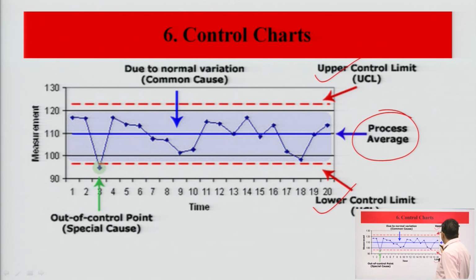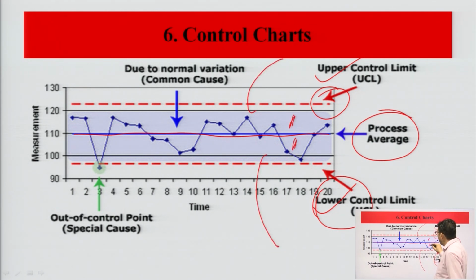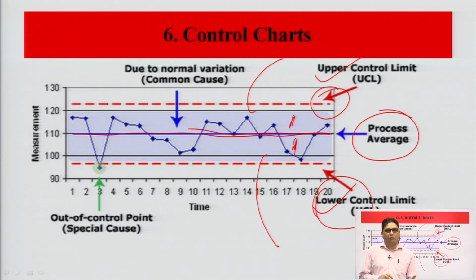So, this is the desired line that we have to maintain in our quality, and this is our upper control limit, briefly known as UCL, and the next is the lower control limit. The quality standard should neither go beyond the upper limit nor below the lower limit. Within these limits they are accepted, and this is where the desired standards are maintained. So, we need to identify where problems are likely to be incurred.